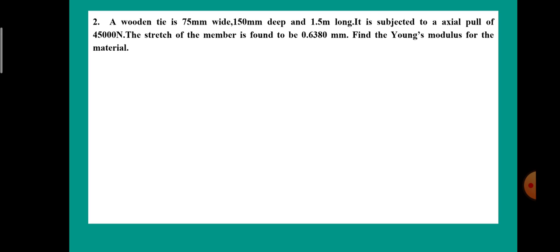So it is then subjected to an axial pull of 45,000 Newton, or it is also taken as 45 kilonewton. Here they have given that the stretch of the member is found to be 0.6380 mm. So they have asked to find the Young's modulus for the material.